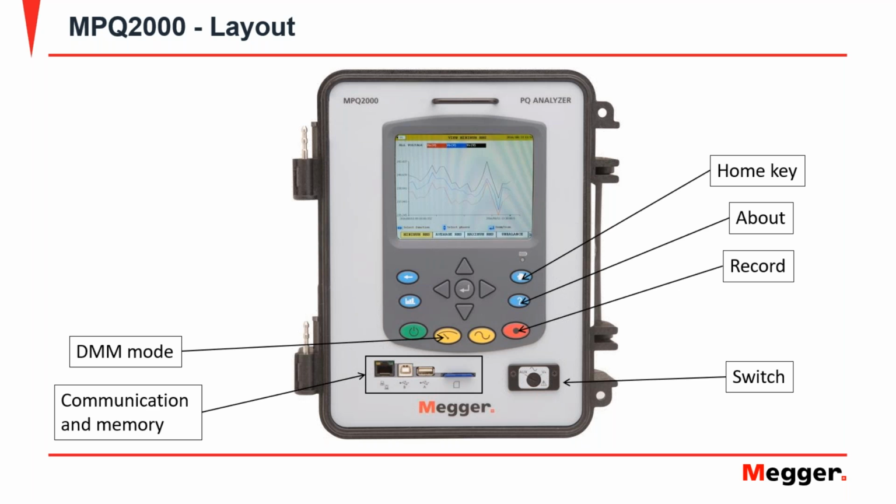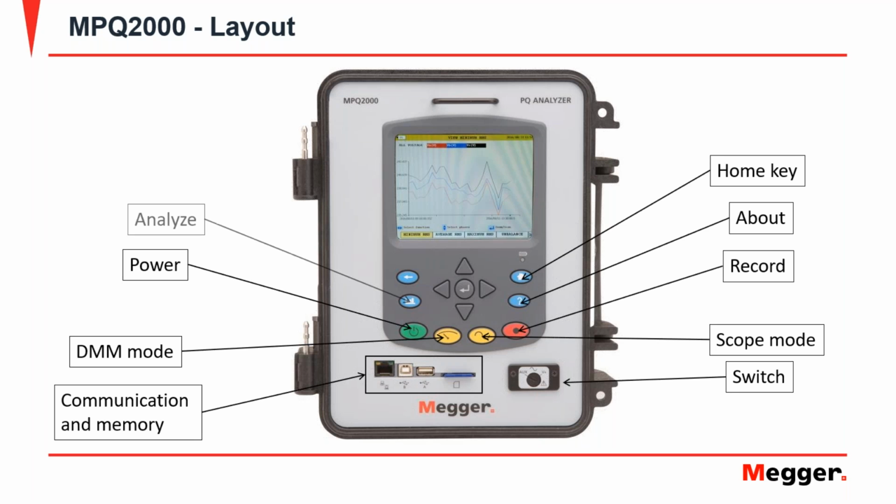There are two yellow shortcut keys there. There are two modes in which information can be viewed: the DMM mode, in which you can look at numbers, and the scope mode, in which you can look at waveforms. The green key is to power on the unit. The key with the bar graphs is the analyze button. If you hit that button, you can analyze the data statistically with the help of the templates that are inside the unit.